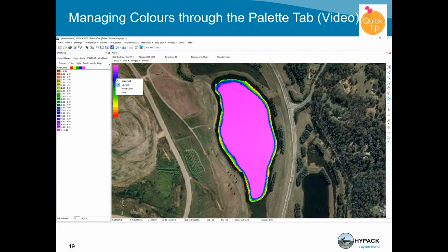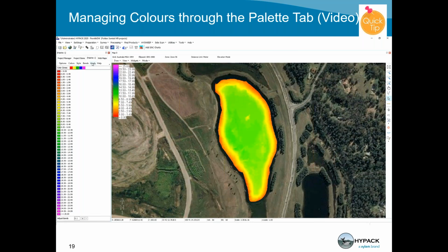So first you show the text. So that gives me here text, and that's in meters. And then I can set a band. So I set a minimum of 0 meters and a maximum. That's my maximum water depth. And I set an increment. For every color, I set an increment. So I said okay. And now I have a color bar. My color bar here at the left side shows me all the colors and the range of the colors. When I press apply, it will apply this immediately to my data that's visible in the map view.